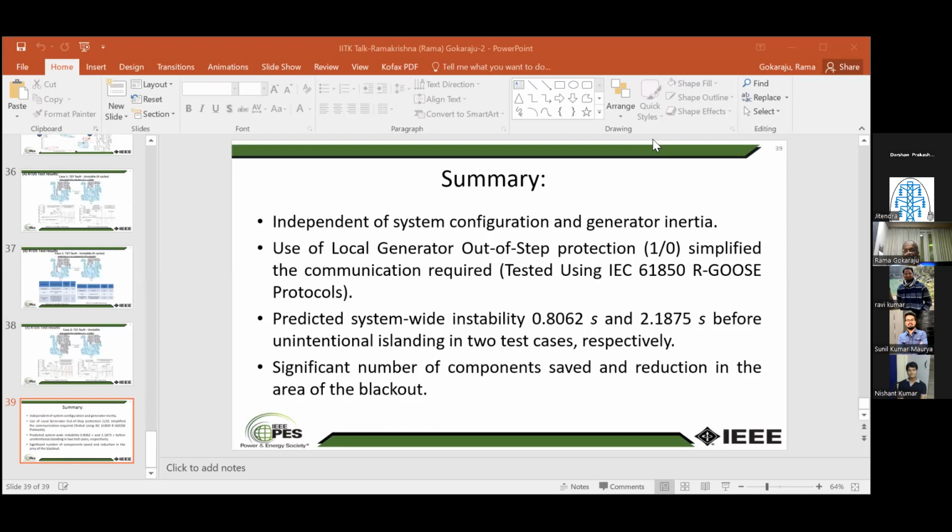On select portions of the line where we want to analyze this out of step condition, based on the local voltage and current measurement, I'm finding out the active power flow on the line. So a disturbance happens. At the trigger point, what was the power flowing on the line? And as soon as a disturbance happens, the electrical power is going to go down.